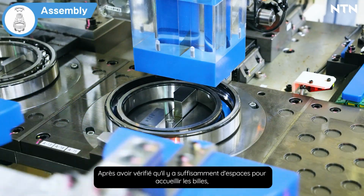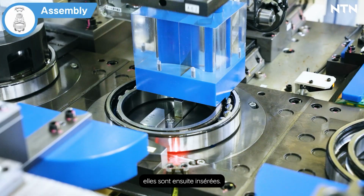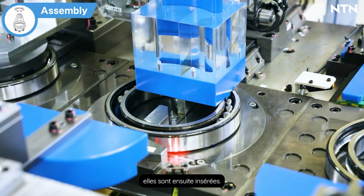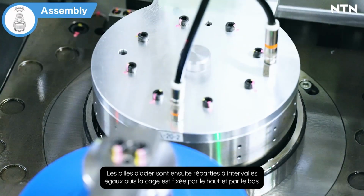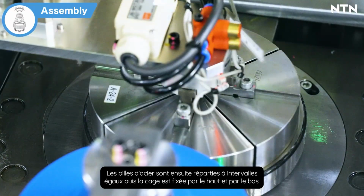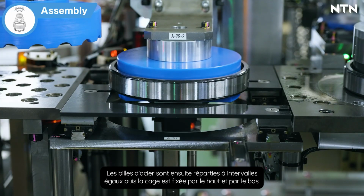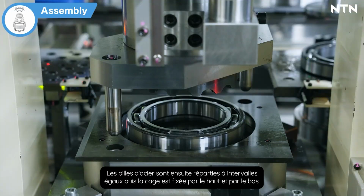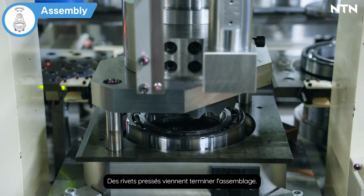After ensuring there is enough space for the steel balls, the required number of steel balls are then inserted. Steel balls are then placed at equal intervals. The cage is attached from the top and bottom, and the rivets are pressed to complete the assembly.